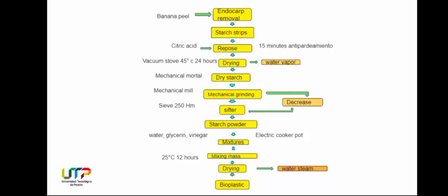To dry, it is recommended to dry it in a stove or oven at a temperature of 130 degrees Celsius for some minutes and then let it rest at room temperature for 2 hours. The second drying option is to let the bioplastic paste sit in the sun for 24 hours or more until the bioplastic paste has a good consistency.